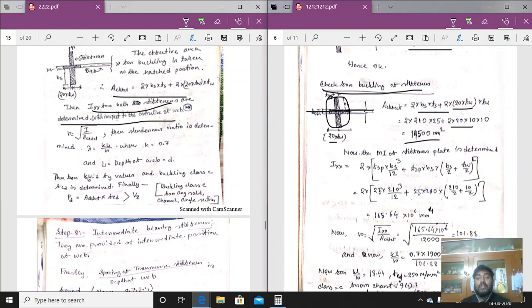So we have to use the formula for the parallel axis theorem. For that plate and that plate, two numbers of stiffener plates are there. So now, two numbers. What is the area? First we have to calculate the moment of inertia of that area, then we have to calculate from this center distance to that center distance, AH square. So IXX plus AH square we have to calculate.